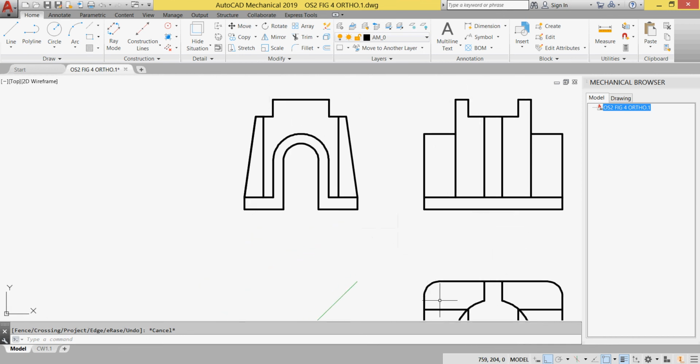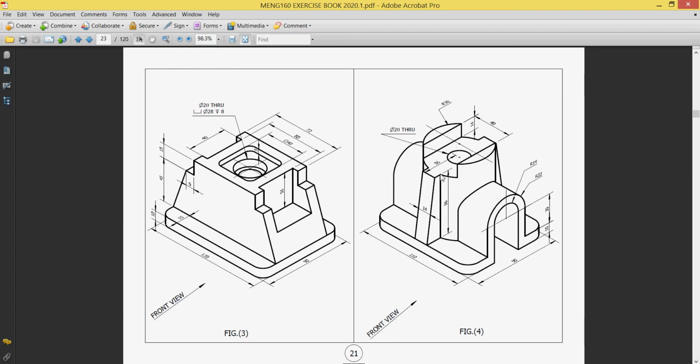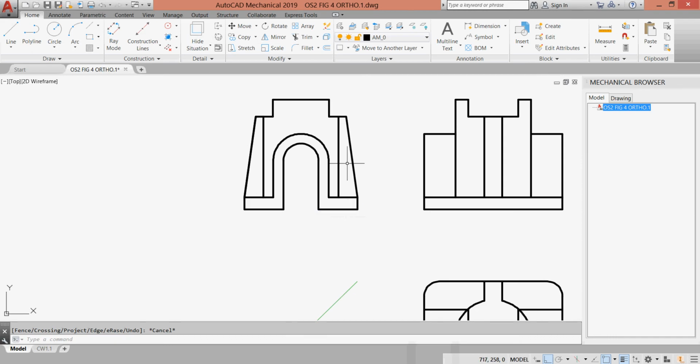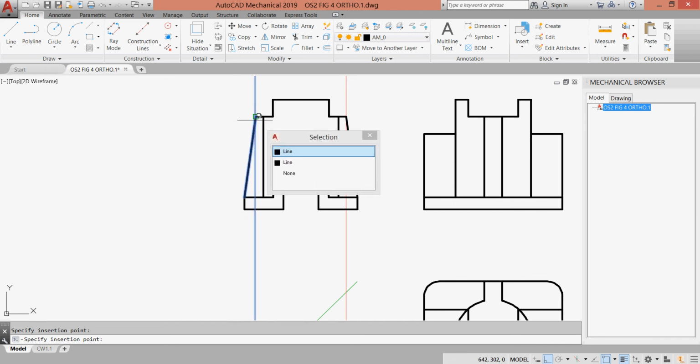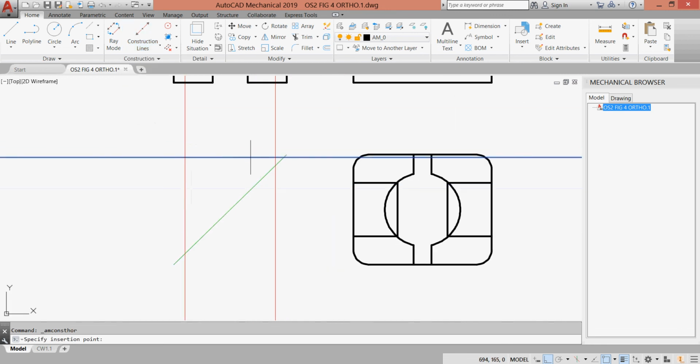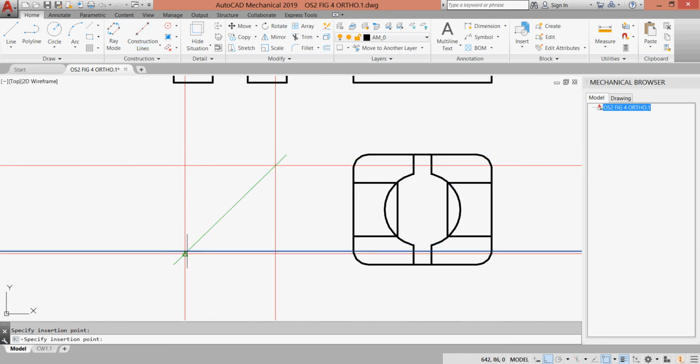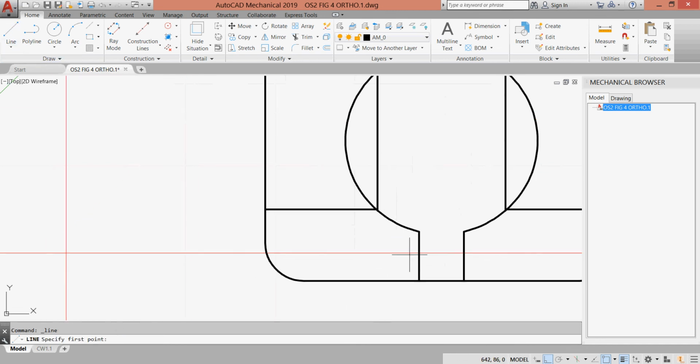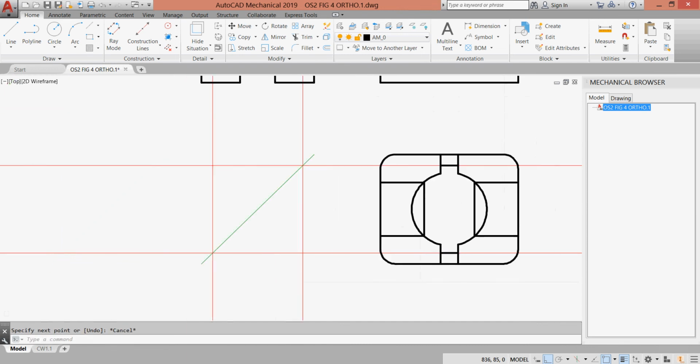But as we see here, part of my web is flat and then goes inclined. So where is it? Here. Just take a construction line from here and from here. This is the end of my flat part of the web, and project it down to the top view. This is the end of my flat part of the web, and part of the web from the intersection.